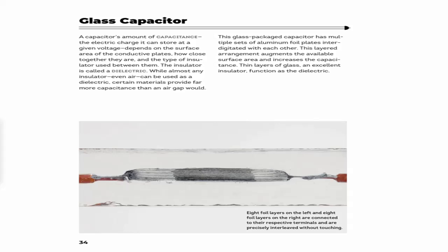The advantages of glass capacitor are, first, high reliability and stability. Second is low loss and high Q factor. Third is high temperature tolerance. Four is non-polar and non-reactive. Fifth is suitable for high frequency applications.